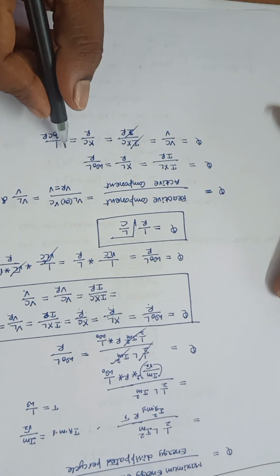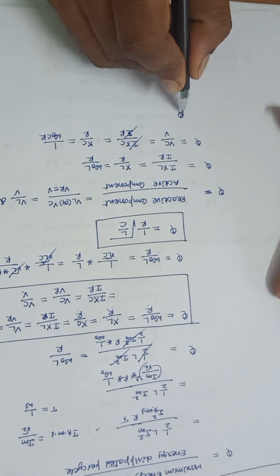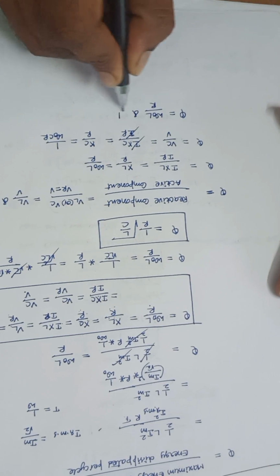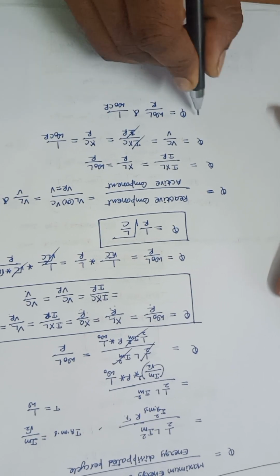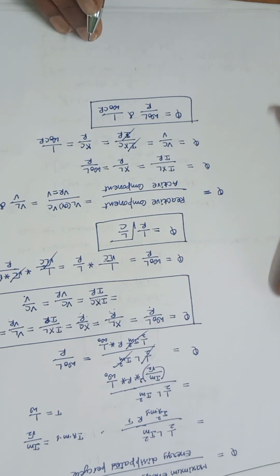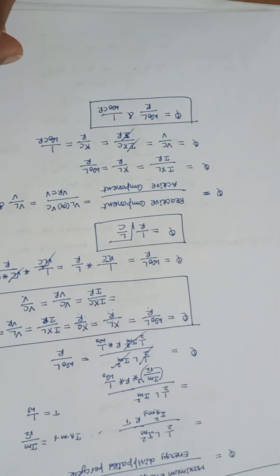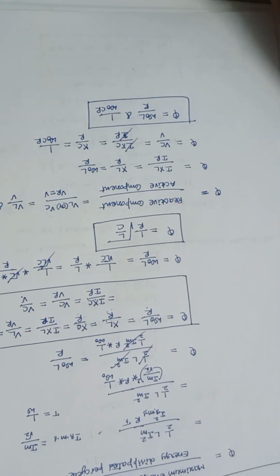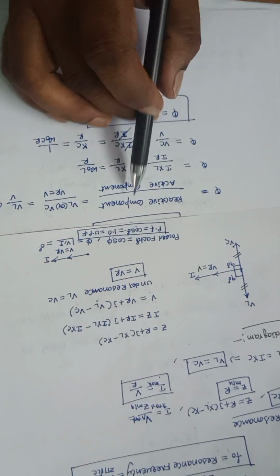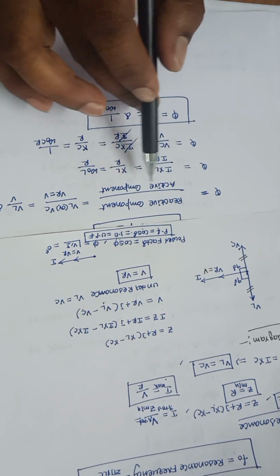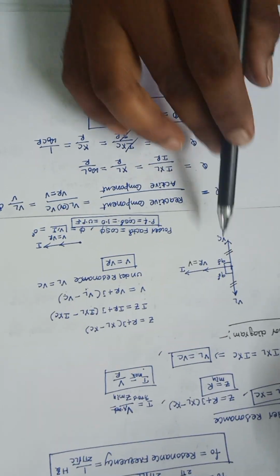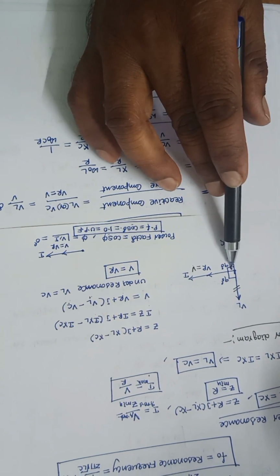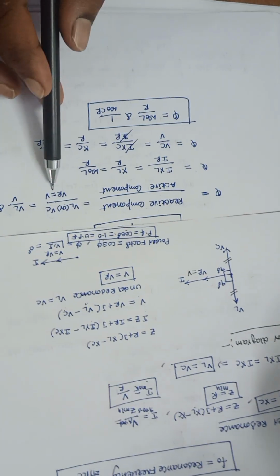I forgot to write the quality factor here. Normally the quality factor we can write as omega naught L divided by R, or I can also write it as 1 by omega naught RC, or omega naught CR. So either way I can calculate the quality factor for any circuit. For any circuit it is better to remember this ratio of reactive component to active component, because in the parallel RLC circuit I need to use this formula to find the quality factor. So the reactive component in the phasor diagram, either VL or VC, both are equal here, divided by the active component, that is VR or V.